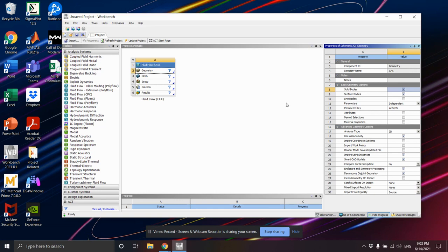Every time that you start any type of simulation or problem on ANSYS, we're gonna select the analysis type. This is where we're gonna tell ANSYS if we're making a 3D or a 2D problem. It's very important, because if you have a 3D geometry and you select a 2D analysis, it's not gonna give you the results that you want. So some things to consider every time that you go into any simulation.